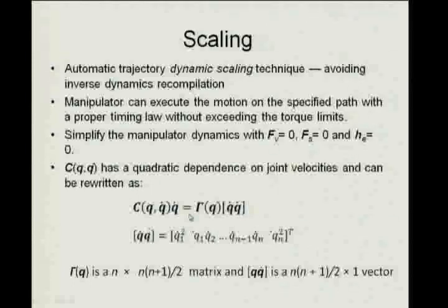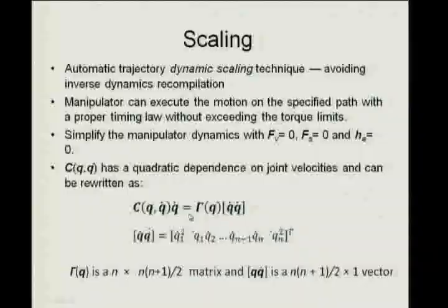I say okay, now let us increase the time that I am doing the whole motion in, and then hopefully I will reduce all the accelerations. You are doing the same motion in this larger amount of time, hopefully reducing all the accelerations. But now if I want to find out whether I have done things right, I will have to compute the torques again.